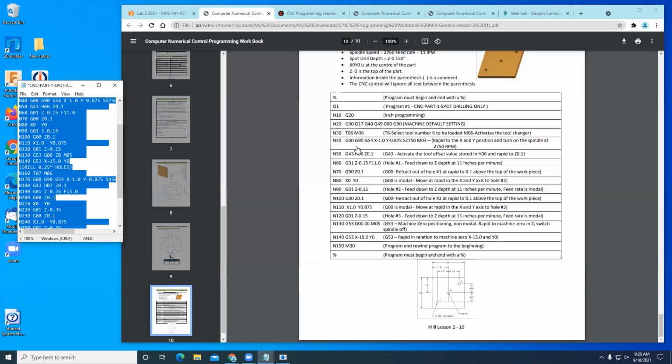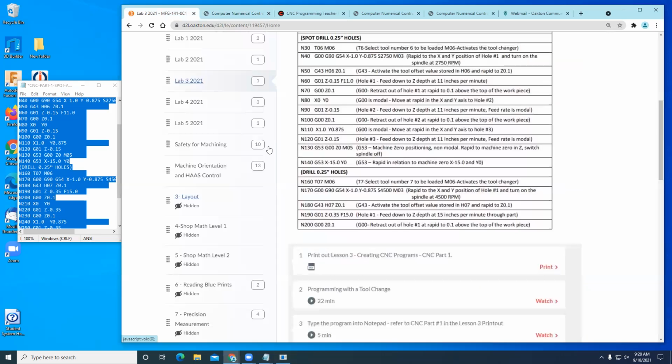Bring it to our next location, tool change, tool number 7. And then we go through and drill these holes. When we set up tool number 7, again, the same standard start line, G0 G90 G54, tells you which origin we're using, and then the X and Y values, and spindle speed is M3 clockwise. Set up our height offset, the tool will hover 1,000ths over the part, and then it will drill into the part, -0.35, retract, go to the next position, drill, retract, next position, drill, retract, home the machine, safety line, and that completes the program. So that's what we can simulate.